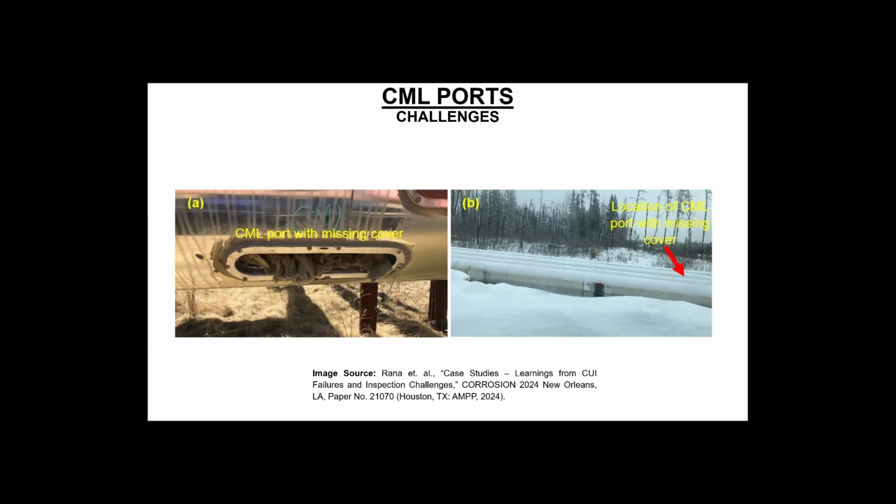And imagine that in the winter time, when there are snow piles, the snow is eventually going to melt, and that will allow moisture to infiltrate these points where the inspection port cover is missing. So that's even going to be a nightmare. These are the practical challenges with the CML points that discourage some owner users from the concept of CML, although CML is known to give high confidence data.